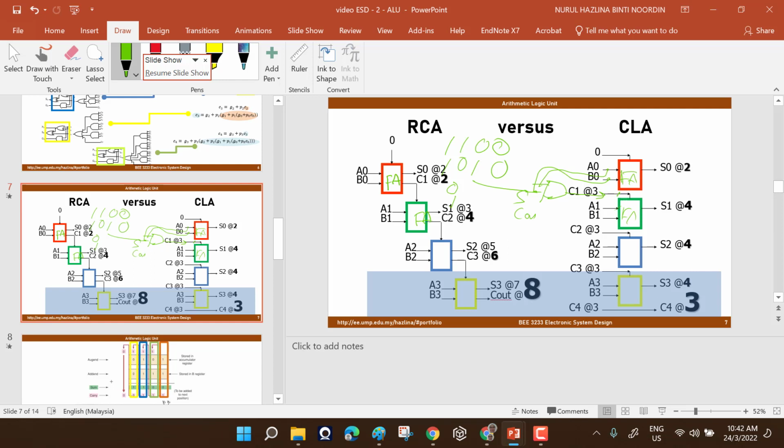Second bit means this: we have A0, A1, A2, A3, and we want to add B0, B1, B2 and B3. So for the addition of the second bit, B1 and A1 here, I need to add the C in. C in for the second stage, right? So this C in, I'm predicting it by having an AND gate located here, so that whatever input comes from the previous stage, I can predict whether it becomes 1 or 0, and then I can execute this. Okay. Now, one stage is not very difficult. This part is settled, you have settled this part, right?